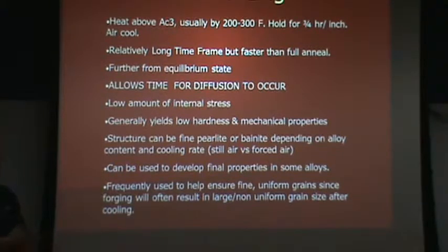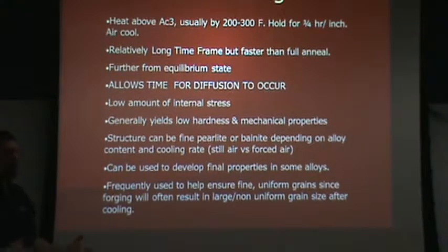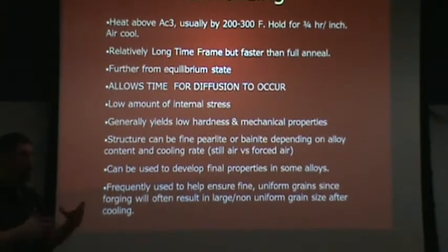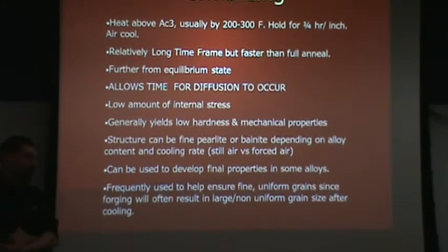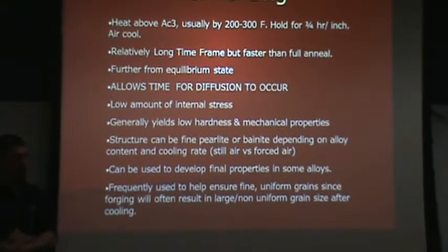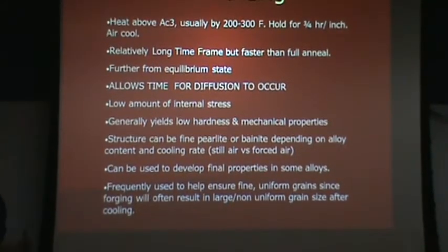And that means that the austenite grains are free to grow to quite large sizes. That's fine when you're doing bulk plastic deformation, forging, rolling, no problem there. But you don't want that large austenite grain size as the precursor to your heat treatment, because the large austenite grains tend to result in low toughness, low ductility.